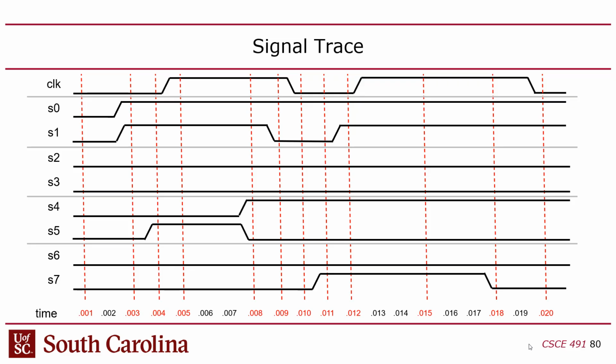It has a variable sample rate. So what I'm trying to show here is that in this case I have 8 parallel signals along with the clock, so there's nine total traces. I only write whenever at least one of them changes. If any one of these signals change, I have to record that. I have to record all 9 signals anytime even one of them changes.